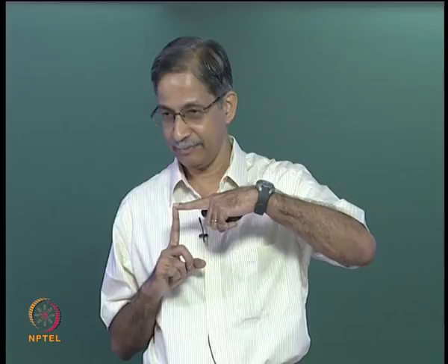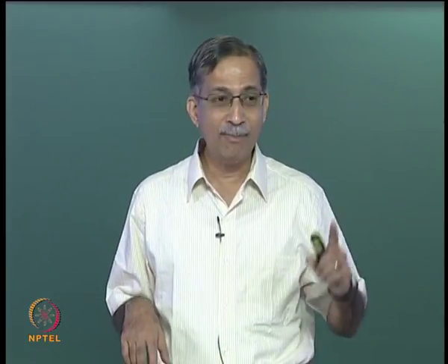Let that be very clear, right? So you can quietly remove the child from the picture and look at the parent. The parent is a cantilever. Now if you apply a moment at joint B in that L-shaped cantilever, do you think anything will go into elements 2 and 3? No. So this is the flexibility method. You really have to enjoy the physics of the problem and get the answer. So you just have to draw this.